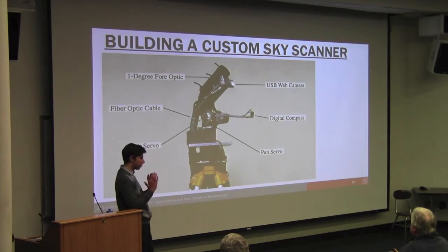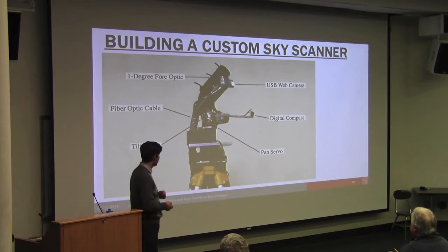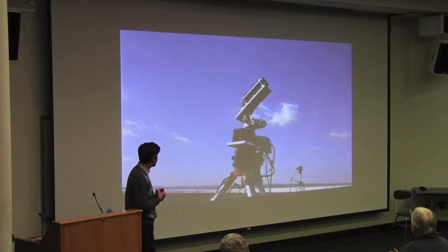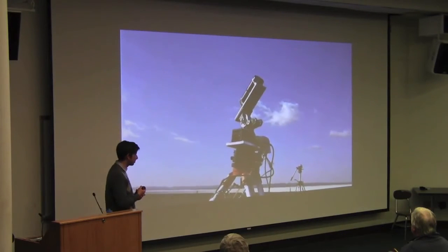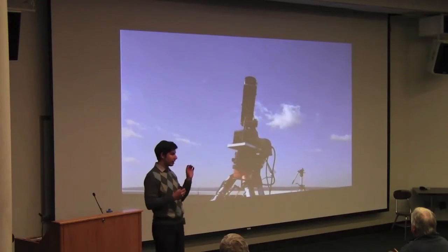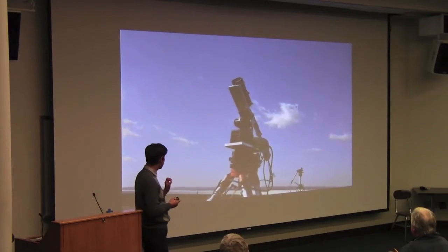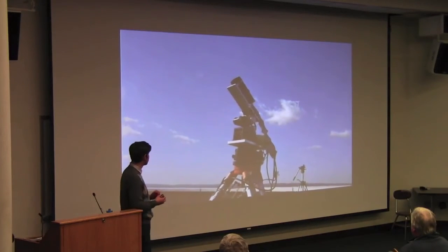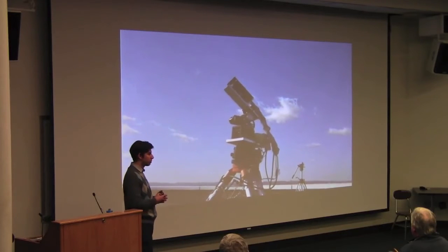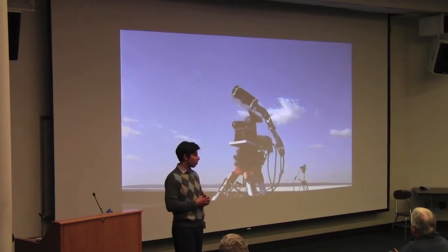I have a compass just to ensure that the direction I'm getting is what I expect, and 2 pan-tilt servo motors to actuate the device into any angle that I want. So it basically goes throughout the sky and scans any pattern I want to do, so I can scan the sky and get the 1 degree radiance component of what that light is actually doing at any given point, which is very useful to both validate the radiometric properties of existing skies and evaluate radiometric qualities of my